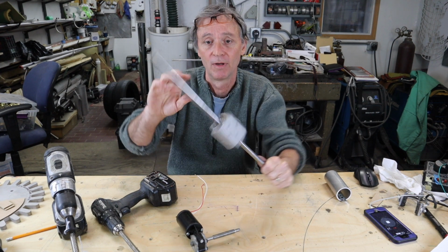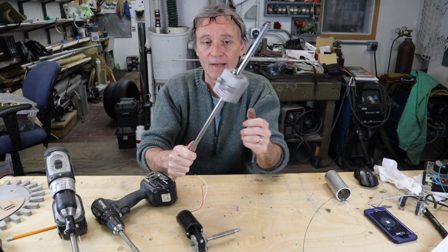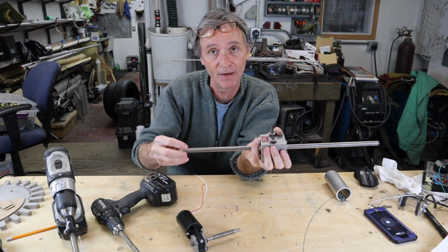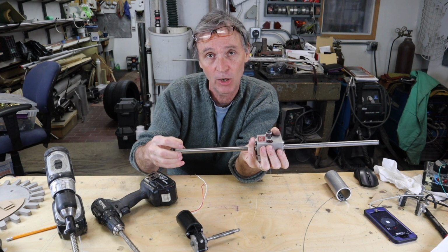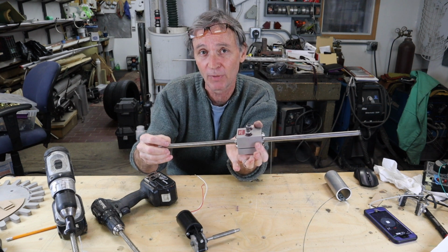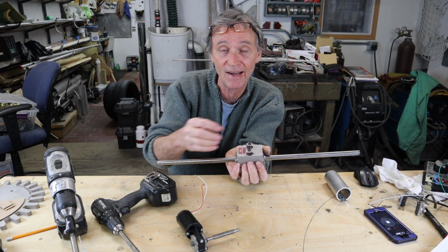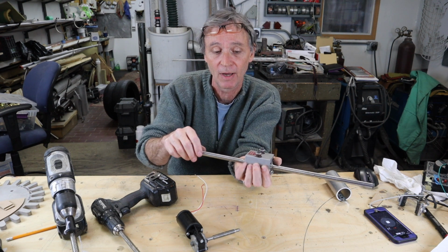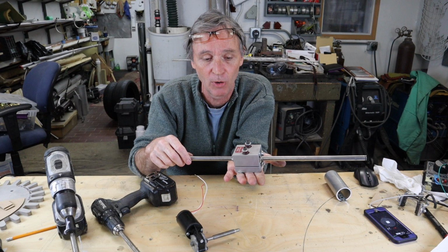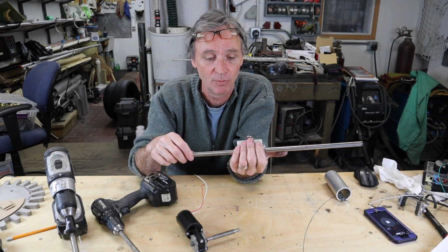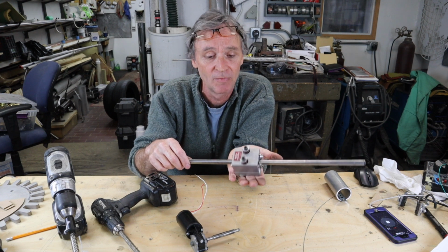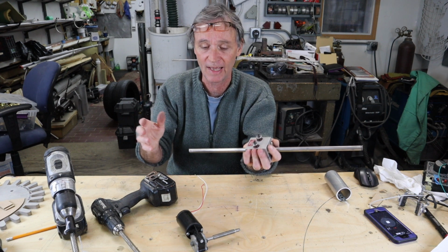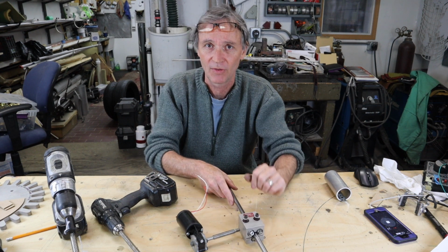this to happen. But obviously what's more likely to be happening is this stays still and you drive it backward and forwards by putting a stepper motor on here, encoding the signal, and then you can repeatedly say go to exactly where you want it to go, stop, move at the speed you want it, and again repeatability for motion control systems, and you can link them up with cameras, motion controlling cameras, so the whole thing can all work together. So that's lead screws.